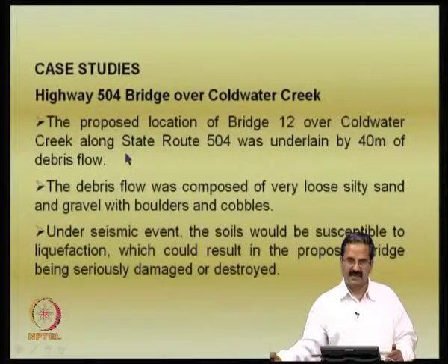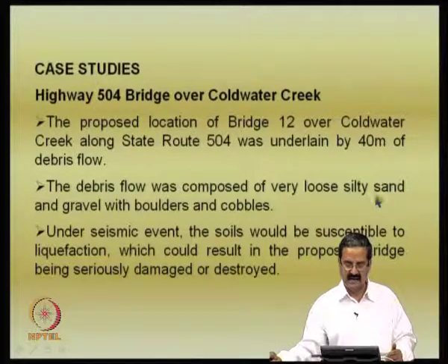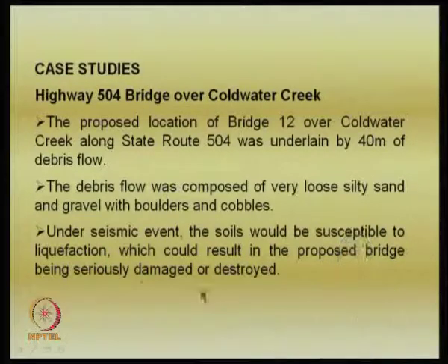There are some case studies here. One is a bridge location, and the soil in this case was a loose silty sand with gravel and boulders. Under a seismic event, the soils would be susceptible to liquefaction, which could result in the proposed bridge being damaged or destroyed. Studies show that the soil has a tendency for liquefaction, and it may cause a lot of difficulties to the proposed bridge, which means that the area should be compacted. In the field, of course, we have studied many methods, for example, dynamic compaction.